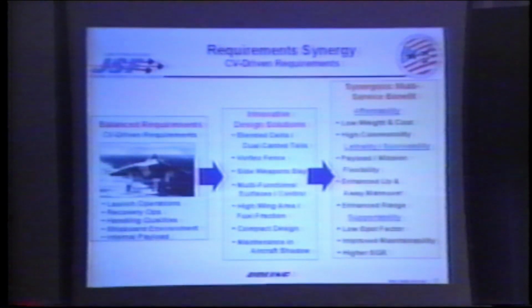Another good example of synergy is the multifunction control surfaces. Typically, carrier approach will drive the design requirements for the integrated flight and propulsion control system in terms of the performance of the flight control surfaces. That driving capability on the Navy version then enhances up and away performance, up and away controllability across the board for the other services. So just a few more examples of the synergistic effects.